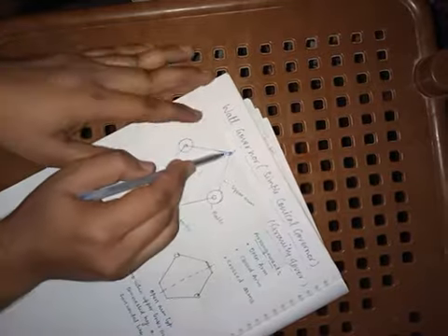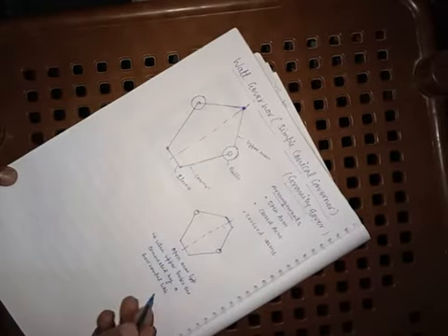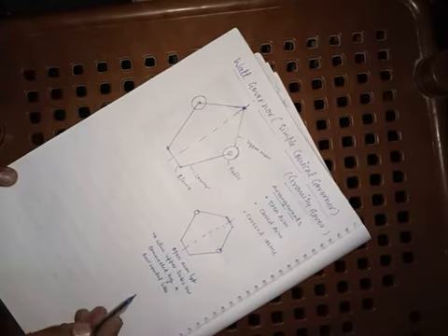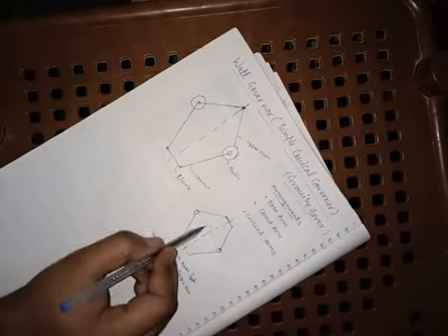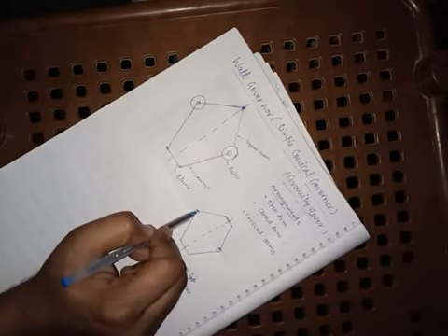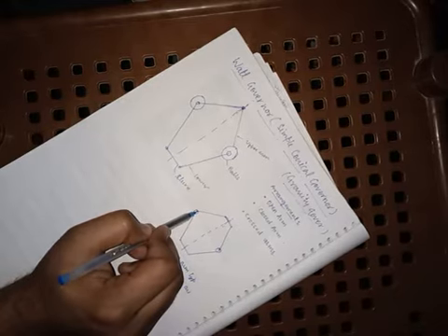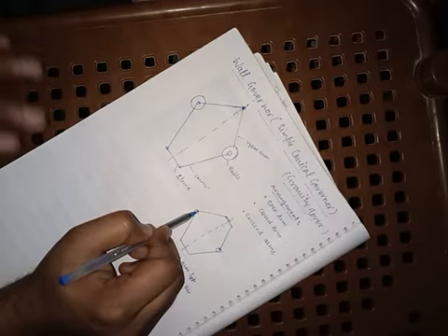Here the upper arms are connected at the spindle axis. And the third arrangement is cross type. In this case, what happens is that the two arms, that is the upper links, cross the spindle and are connected by a horizontal link like this. This is the spindle axis.